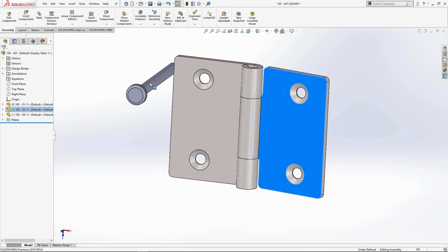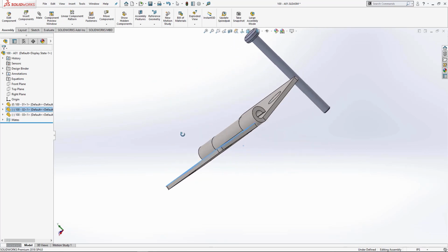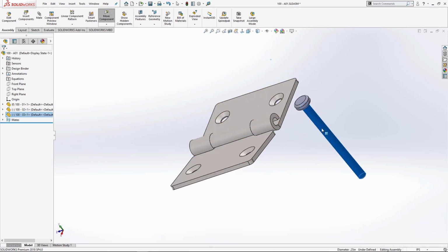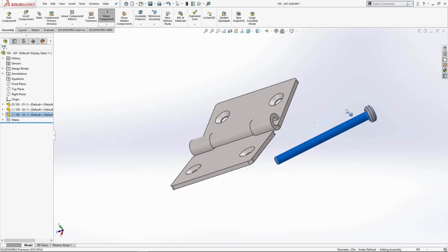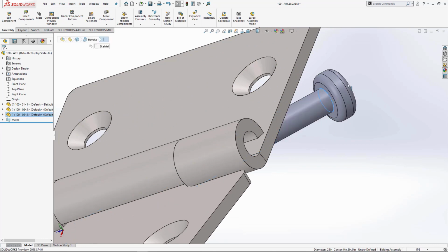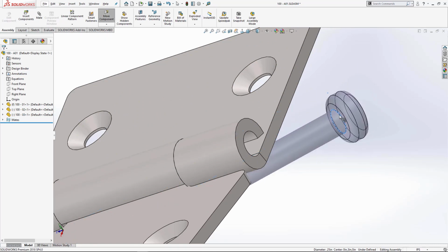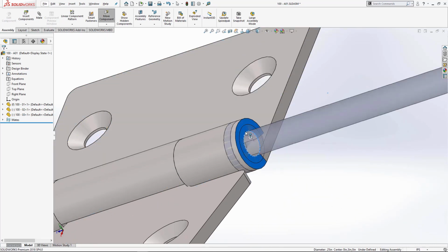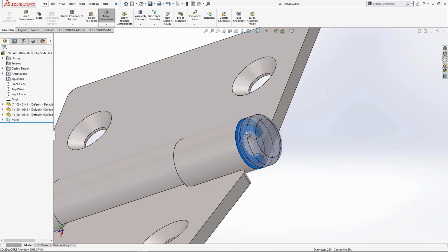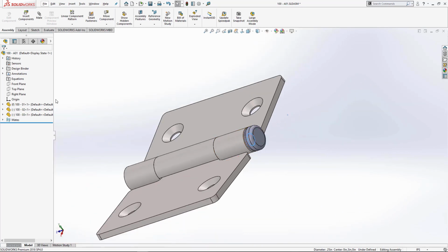All right, let's check another thing real quick. Kind of rotate around to where I can see this little edge. And same thing, rotate around to where I can see the little inside edge there. So here's what I'm going to do, grab this guy. If you hit the Alt command, just tap it one time, then you can do this thing, pin and hold. If you tab, it flips around to the other side. I can drop it in there, and it automatically constrains that.